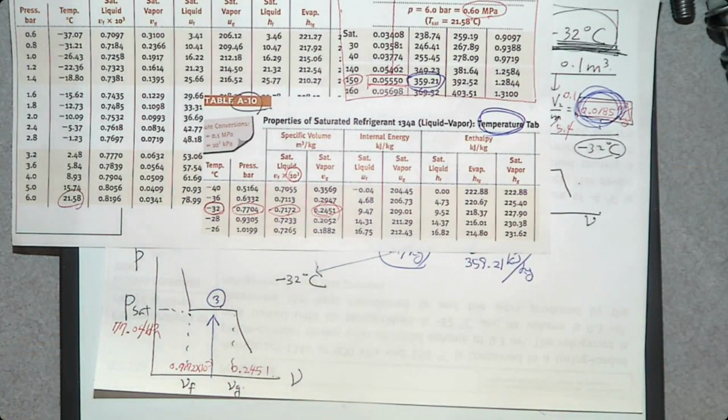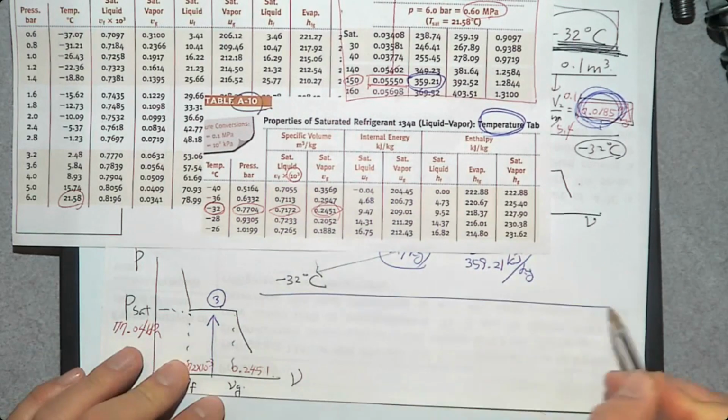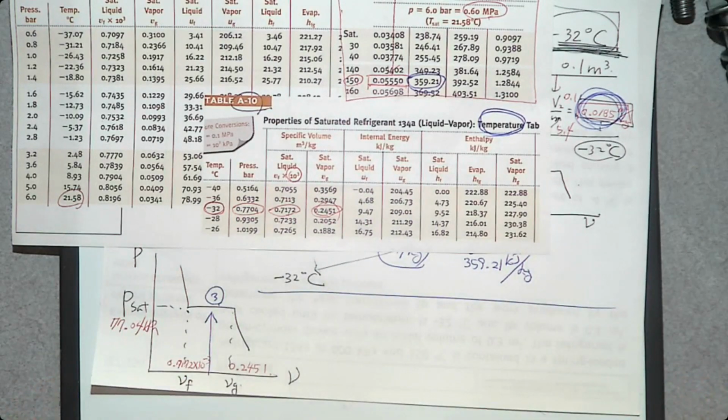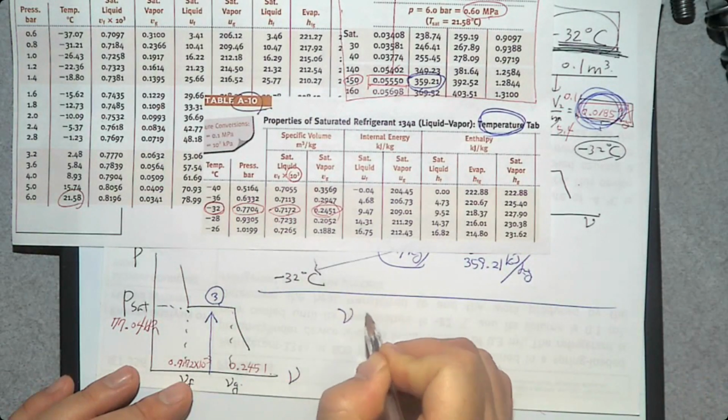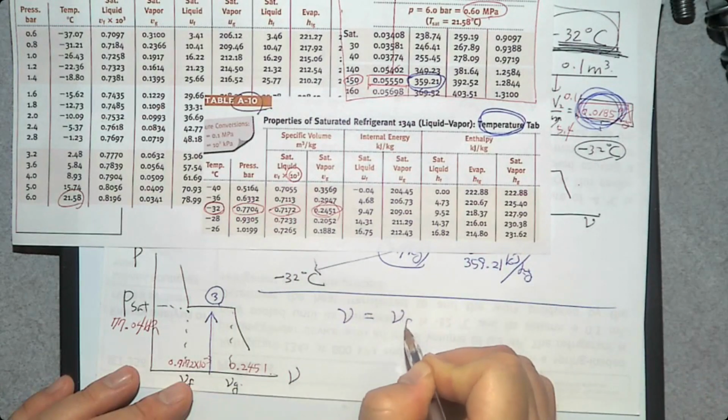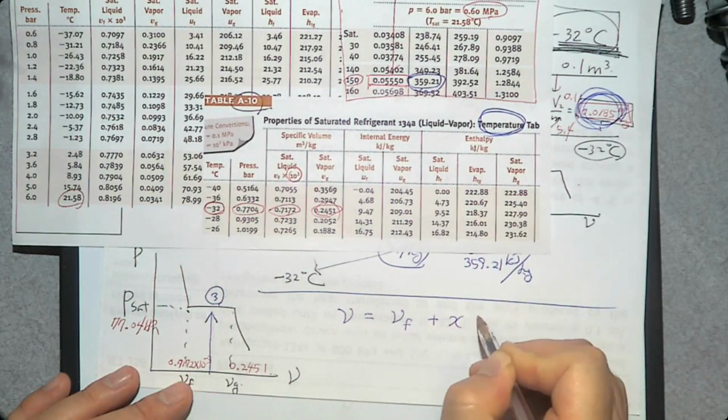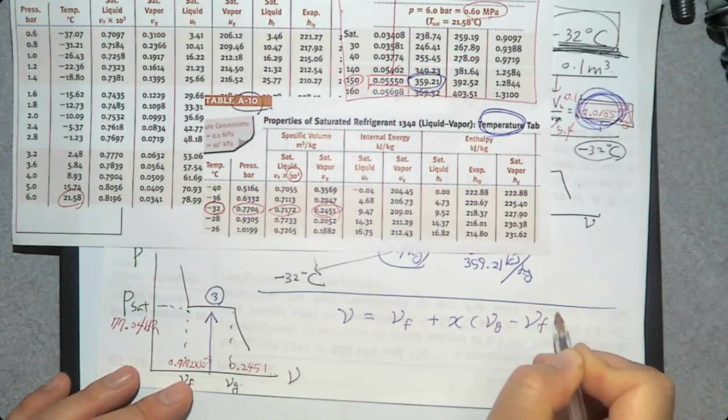So if you have a saturated mixture, how do you determine its properties? We need to evaluate one more property when you have a saturated mixture. What is it? Quality x. So let's find quality x. The problem is pretty lengthy, right? That's a typical problem when you have a phase change material. So let's use linear interpolation to determine the quality x. v is vf plus quality x times vg minus vf.